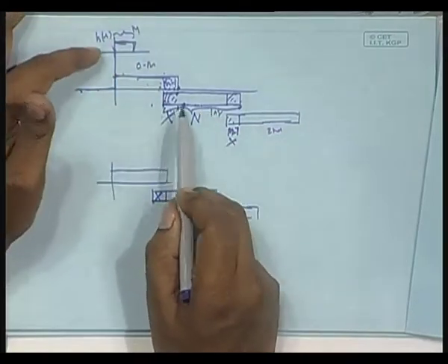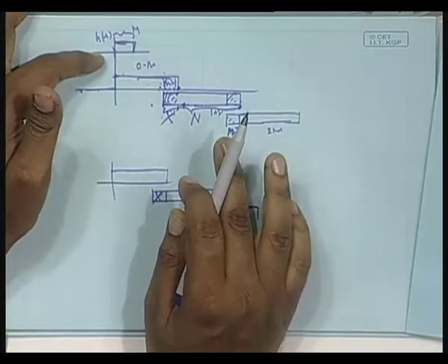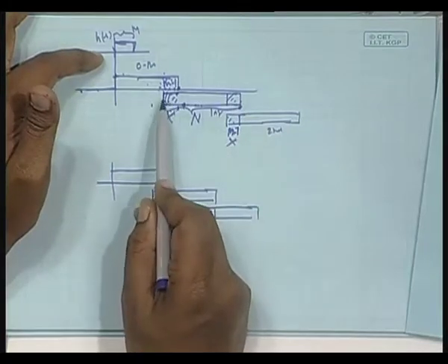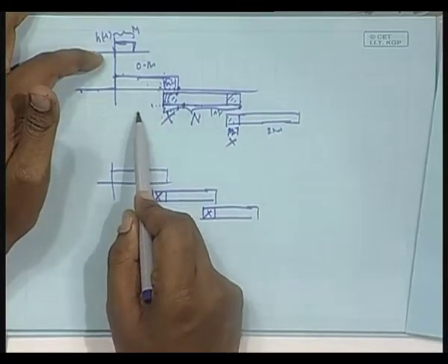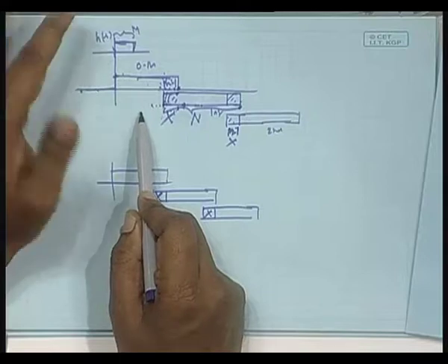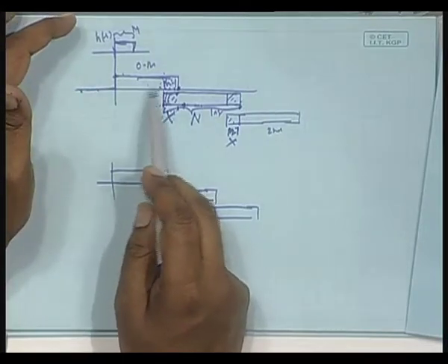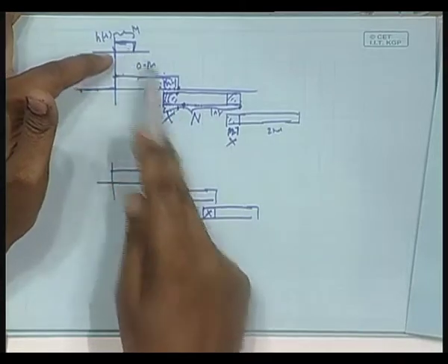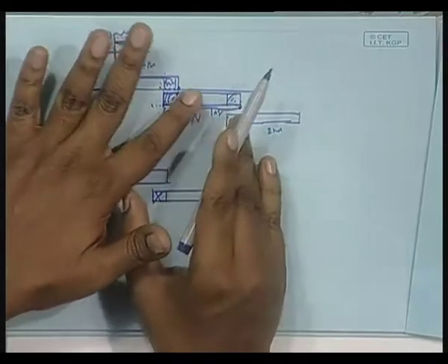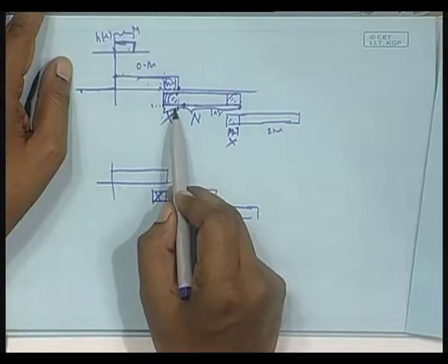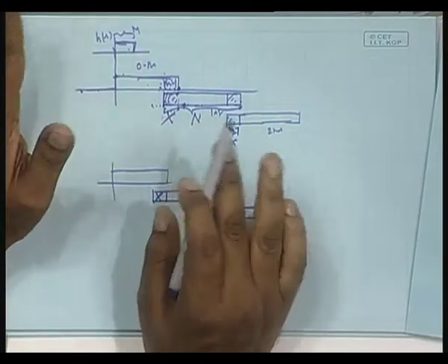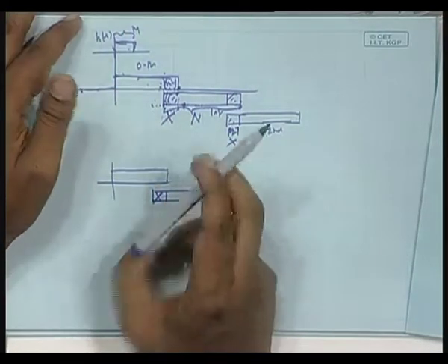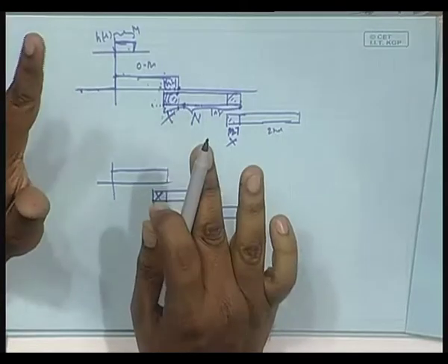Only the first m minus 1 samples are wrong, we know, because they are assuming 0 values to the left, whereas actually there are data, and they are assuming the same filter weight, or the filter weight has changed, and I am putting back the correct one. But even then, first we calculate the linear convolution, then only I will throw away this part, isn't it?